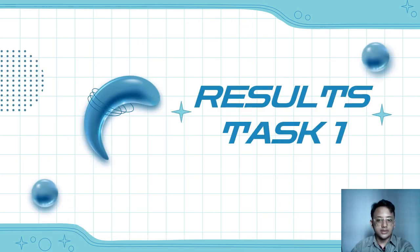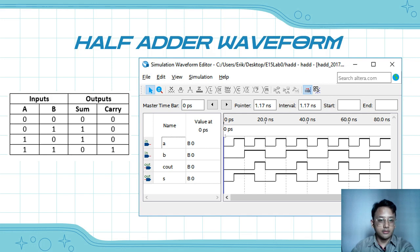So for the result of task 1, we get the half adder waveform as shown here. Let's say we take the inputs A and B equal to 0, the sum and carry equal 0. So we compare with this waveform: if A and B equal 0, then C and S equal 0.